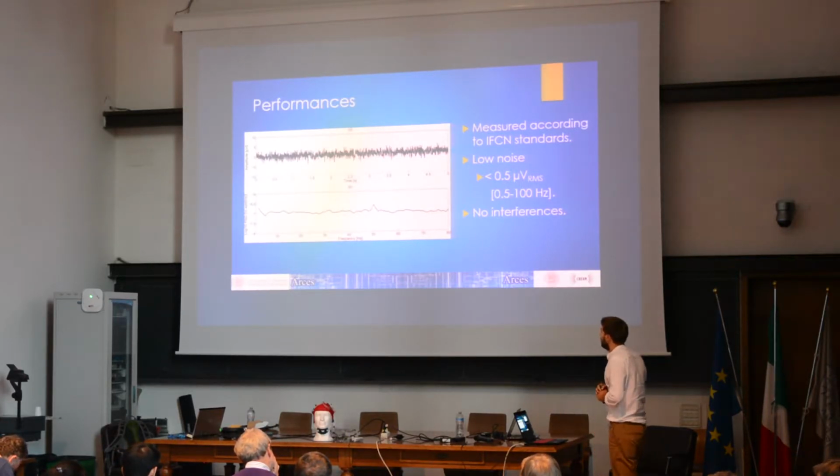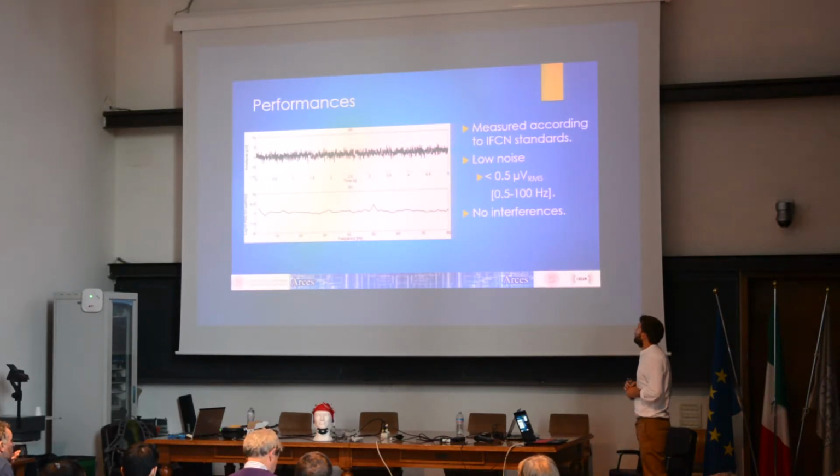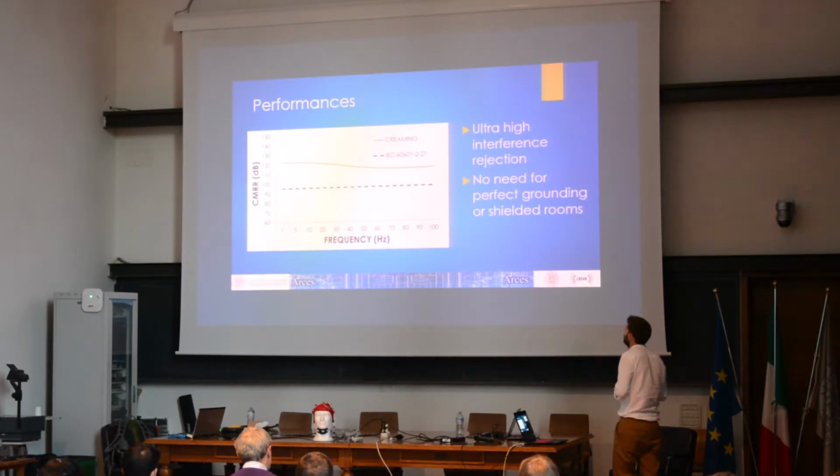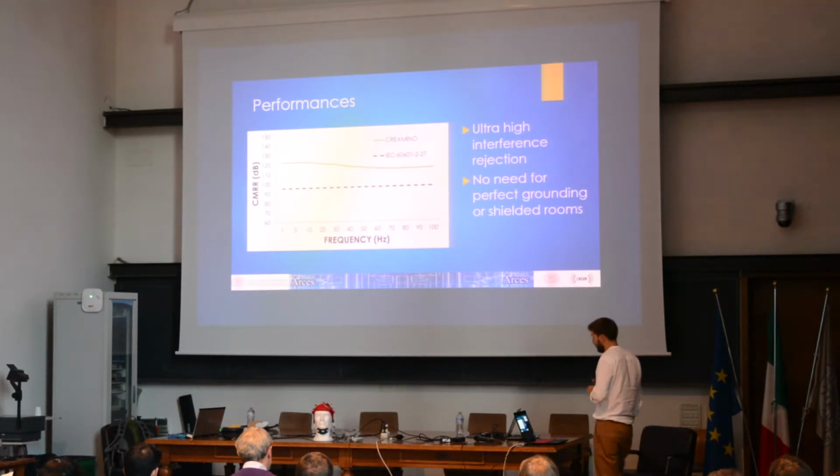The integral of the power spectral density in the 0.5 to 100 Hz band is lower than 0.5 microvolt, which is the value imposed by the standard. In addition, this is the common mode rejection ratio, which is 6 times higher than the level indicated in the standard.